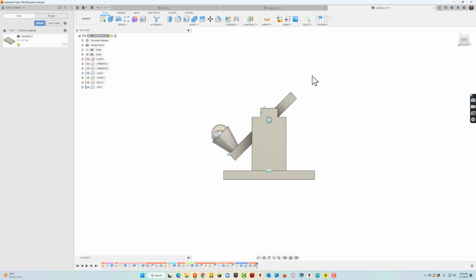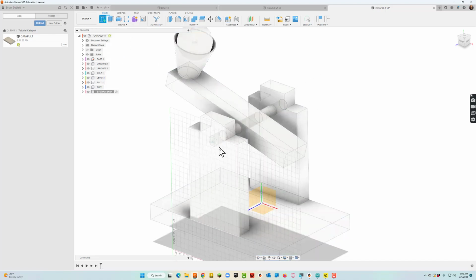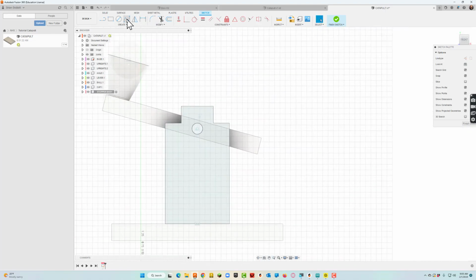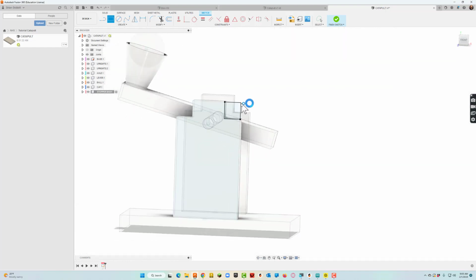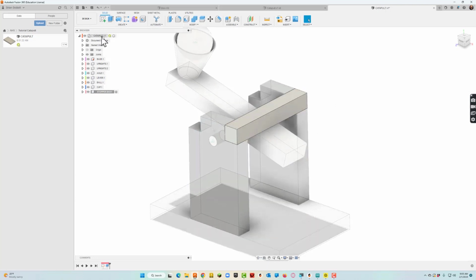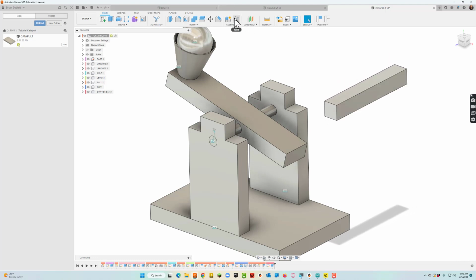And this is one of the reasons we model things in CAD. So I'm going to draw a stopper, and I think what I'll do is just call it the stopper bar. And then I'll come over here to the side of one of the uprights, because I'm going to use that geometry that's already there. Just come up here and draw us a square, and then I'll extrude it across. It's very similar to the axle, right? So that's also going to be a -5, just the way I drew it. Then I'll come back up to the entire catapult. There it is. I'll go ahead and joint this thing up.